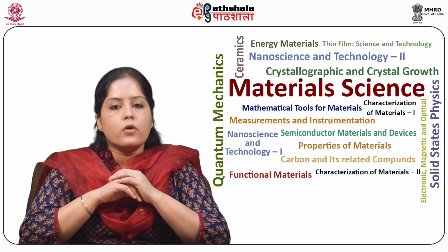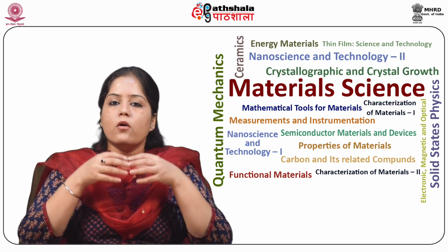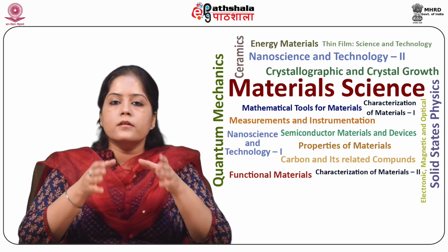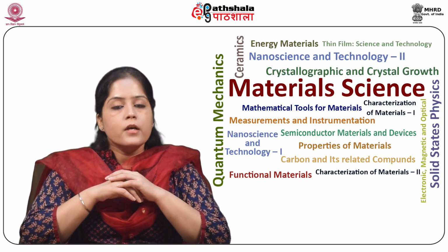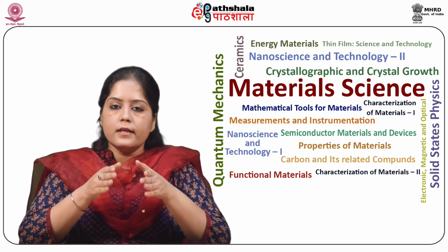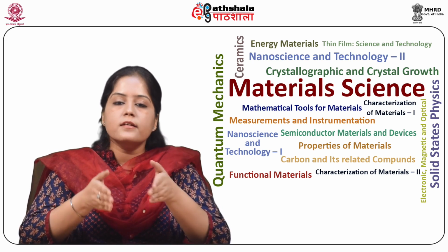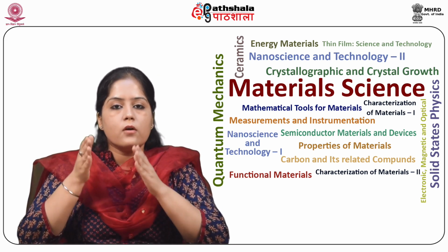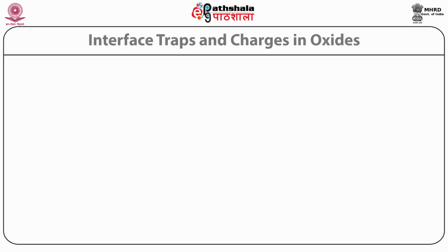Generally, QF is positive and depends on the oxidation and annealing and on silicon orientation. When oxidation stops, some ionic silicon is left near the interface, resulting in positive fixed oxide charge.